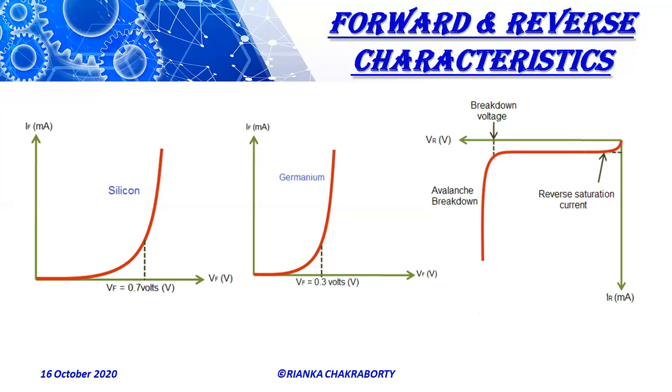In n-type and p-type semiconductors, a very small number of minority charge carriers is present. So, a small voltage applied on the diode pushes all the minority carriers towards the junction. Thus, further increase in the external voltage does not increase the electric current. This electric current is called reverse saturation current.